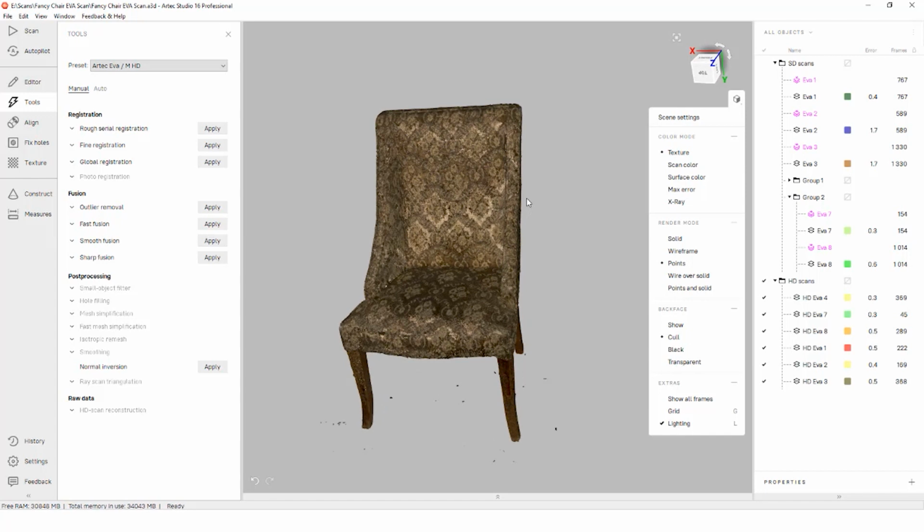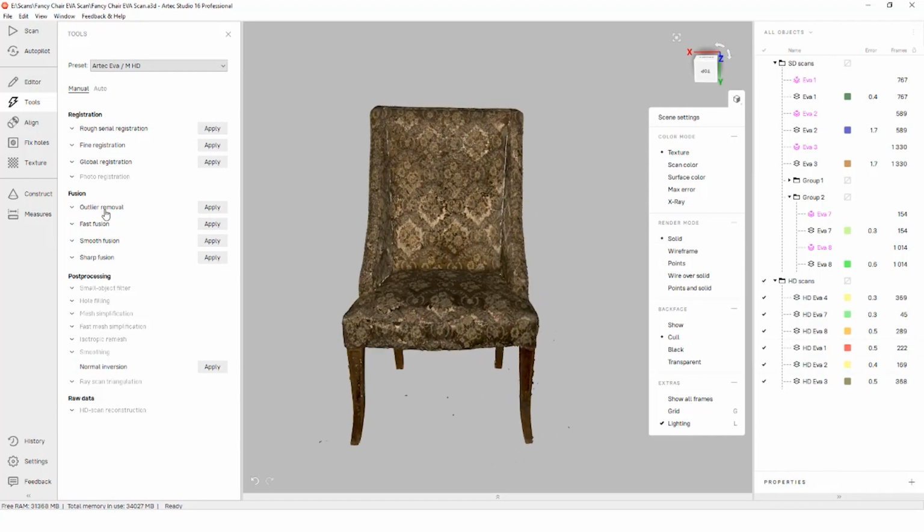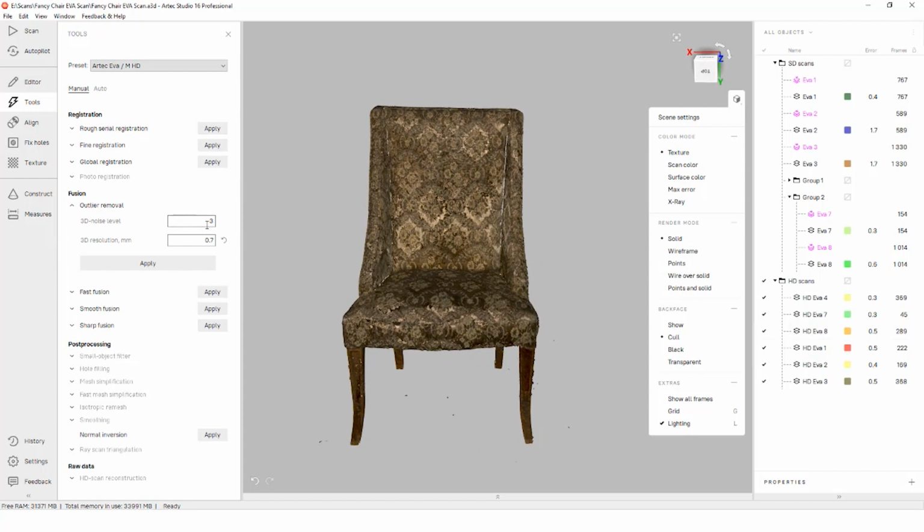but outlier removal can be used next to clean up miscellaneous data floating around in our scan. For the Artec Space Spider or standard definition scans, this step is almost always required, and we'll look for features within a scan larger than a set value and filter that data.